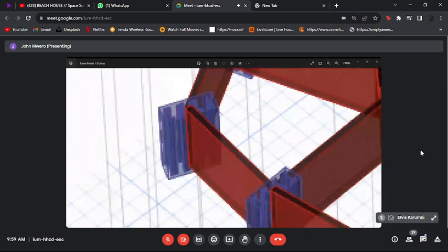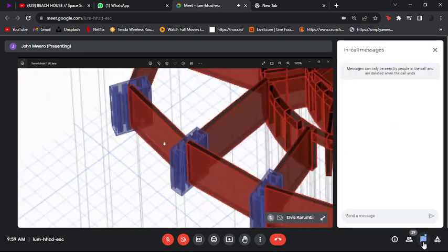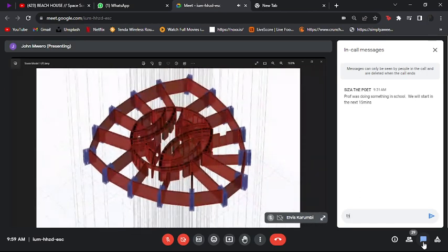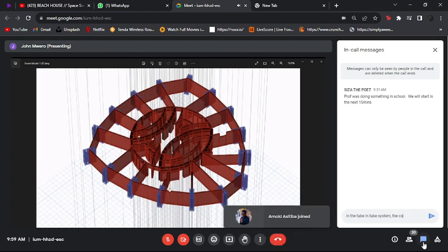I don't know whether you can see that. So there's a steel section within the concrete column. So they're heavy, huge composite columns that are external. So initially a tube in tube. Then in analysis, we found that this building was swaying too much. So we picked a few floors and made them into this system, which we call an outrigger system.